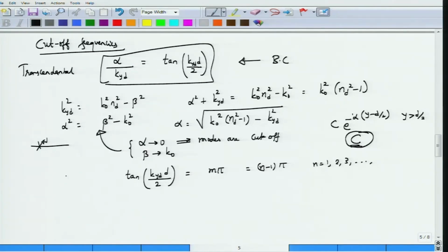So either the first mode will be TE 0 mode or TE 1 mode. TE 1 mode would indicate a half cycle, TE 0 mode would indicate no minima in the region. So these are just two different notations, but the essential idea is that these mode designations follow because they are getting multiples of pi and making the tan of this expression equal to 0.